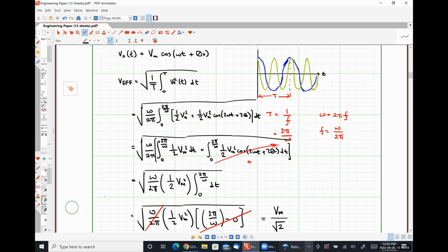The reason why I say that is if you were trying to design some sort of power system, like I've had to do in the past for regions outside of the United States, where power isn't distributed using a 60 hertz AC standard, using effective values means that your frequency doesn't particularly matter. All of your relationships will still work, and so you can just work in this RMS domain without having to deal with all the other consequences, right?